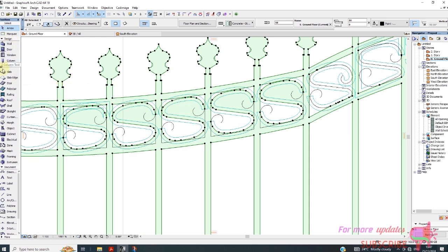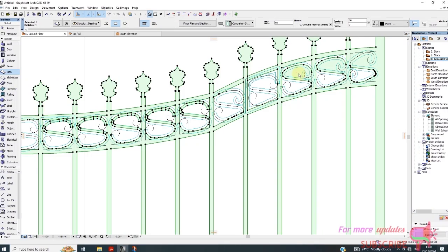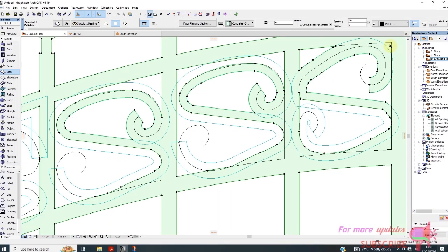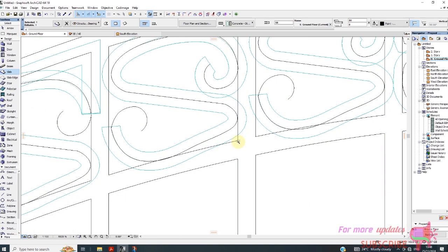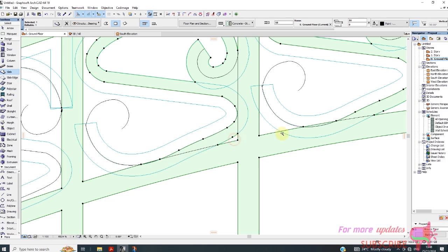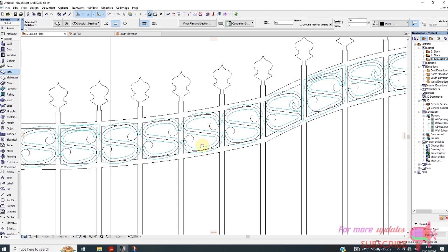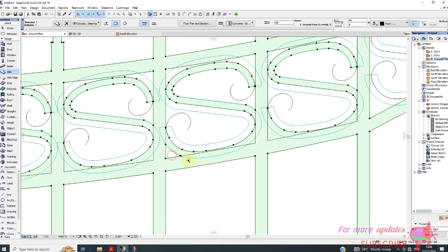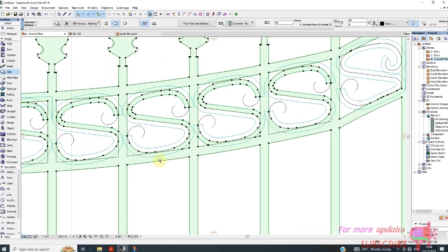So I'll go and activate slab again, holding that, and I'm deleting those parts now. Holding space. And make sure the slab is activated so that you can remove unwanted parts using magic wand when you hold the space button on your keyboard.